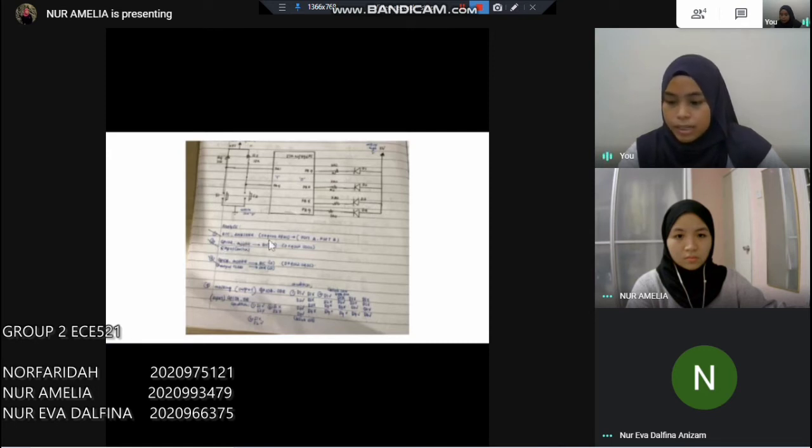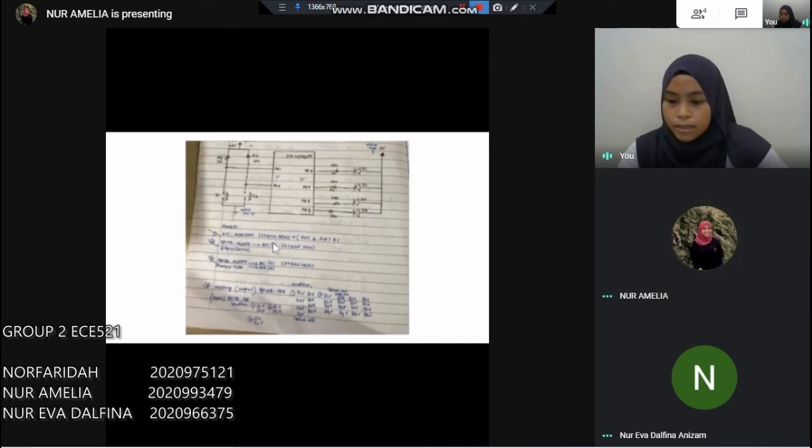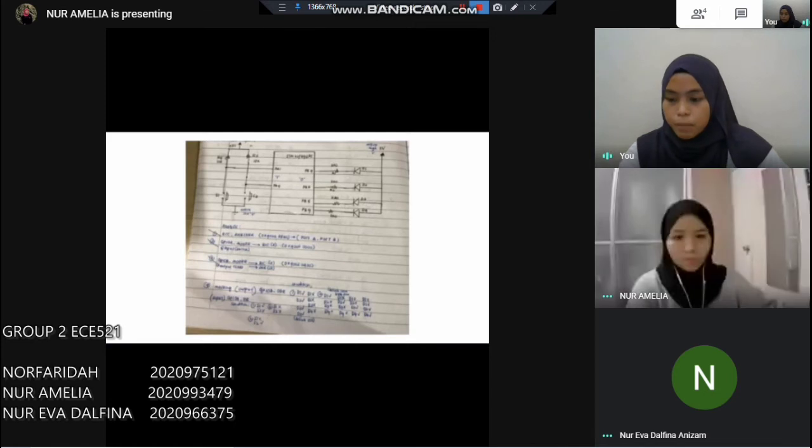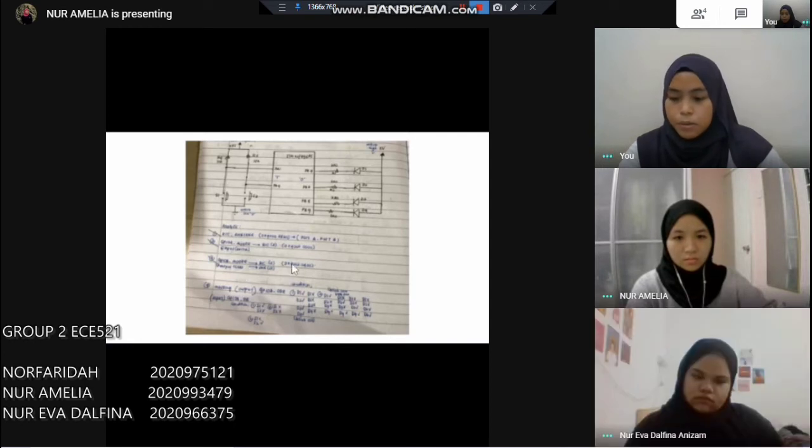For our RCC AHB1ENR, we know that the address used is 0x40023830. For GPIOA MODER, we have our address of 0x40020000. For GPIOB MODER, we have our address 0x40020400.